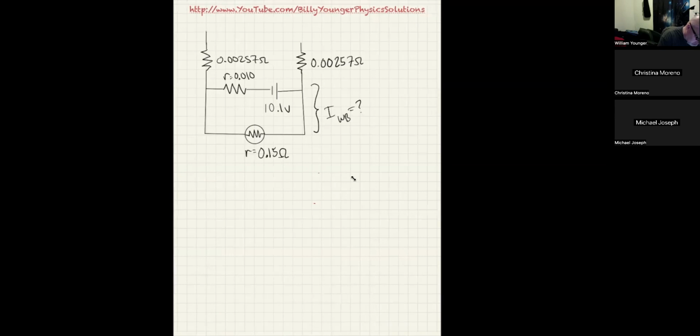And now from there, I'm going to go up to here and to here. And what I'm going to put is a battery that's actually in good shape. But oddly enough, despite being in good shape, it seems to have a higher internal resistance than the bad battery. That's the mistake I think he made. And I don't think he realized he made it because it was made in the figure drawn by some artist that, you know, he didn't draw. That one has a voltage of 12.5 volts. So your job is to work this out.